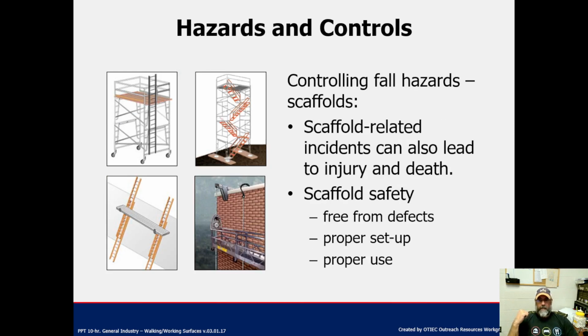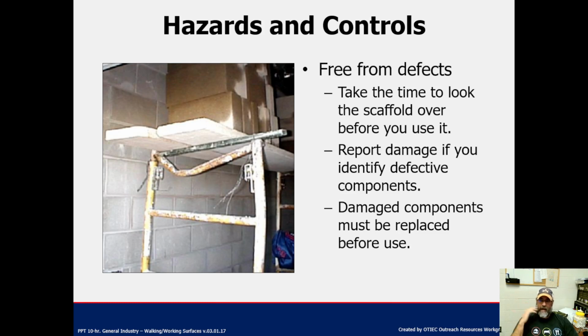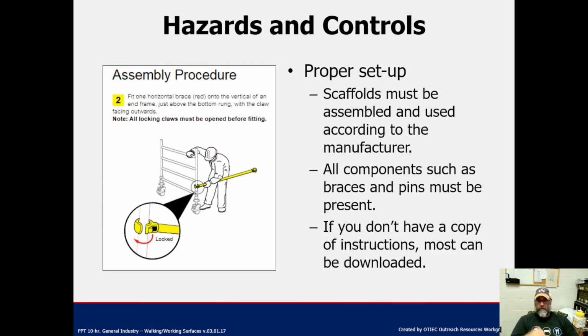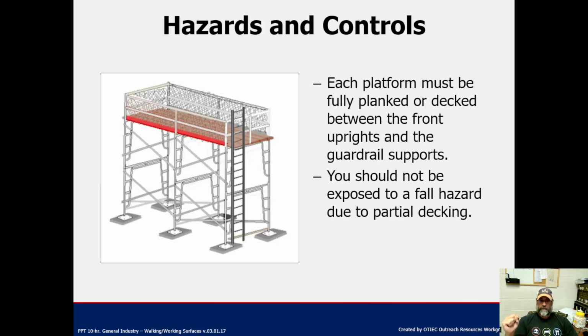Scaffolding needs to have proper decking, properly set up. That is obviously unsafe. I wouldn't use it. You know, if you're dealing with unsafe equipment, you need to notify your supervisor, have these things straightened out. Make sure that everything is set up properly. Follow the manufacturer's instructions on these. All of your platforms need to be fully decked. They need to have guardrails. The railings, they have to have an easy way to access them. I mean, if that ladder's not there, how do you get up there?